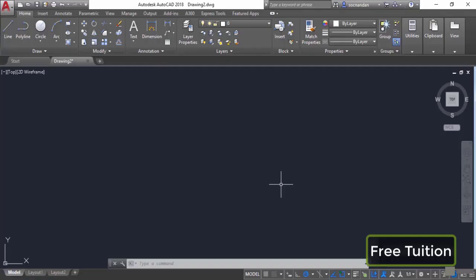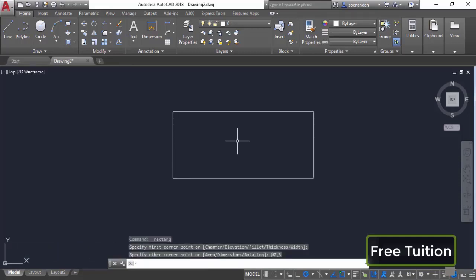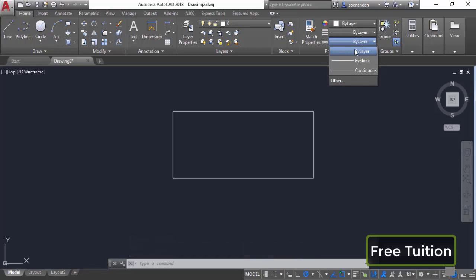So here we have this drawing, and I'll start with the rectangle. So I'll go to rectangle tool, click at a point. Now I'll type add on the command line and then 7,3 and press enter. So there we have it, the rectangle. Now we need to assign hidden line type, and to assign it we need to first add it in the list. So when I go to properties and I click on the drop down, you'll notice that we don't have the hidden line type. So we need to add it here.